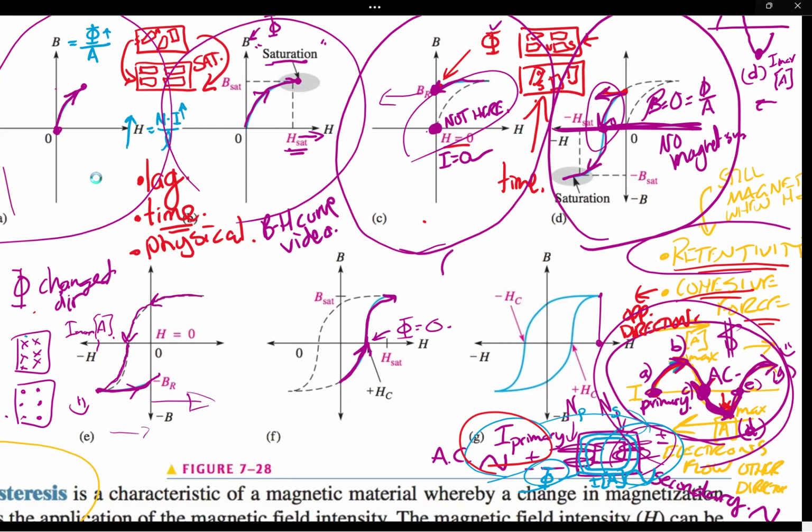So in conclusion, I'm putting a sinusoid of current in amps into the primary side of a magnetic circuit. Because that is a changing current, it's inducing, Faraday's law, magnetism inside the core, magnetic flux lines in the core. But those magnetic flux lines are also growing and collapsing, growing and collapsing. So Faraday's law is telling us that on the secondary side of this transformer, it's also going to be inducing a current on that side. Well, I only paid for the primary side. I got the secondary side.